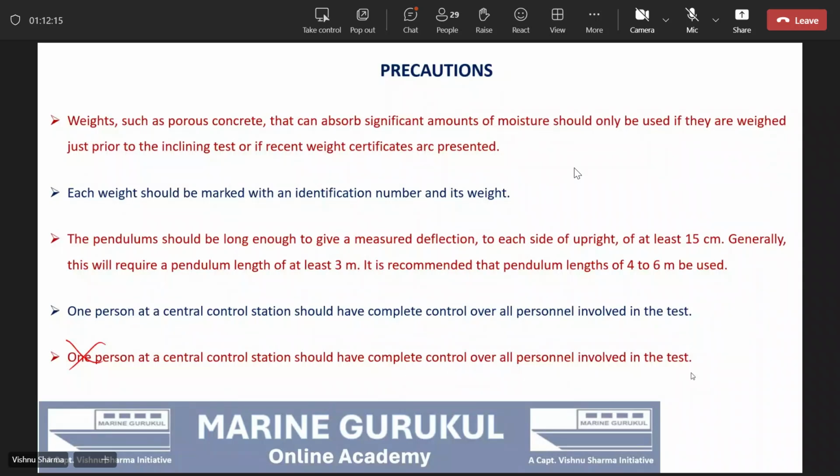But in our MTI also they taught like this, that it has to be immersed. It is not necessary. What is the purpose? See, I have never said that don't use it. I said, what is the purpose of immersing in a bath? The purpose is to stabilize the bob so that you can get the readings, right? Yes, sir, correct. But if it is stationary, then why do I need to immerse it in a water bath? Am I right? Yes, sir, understood. Thank you, sir. Everything has a purpose. So if there is a need, you can use it.